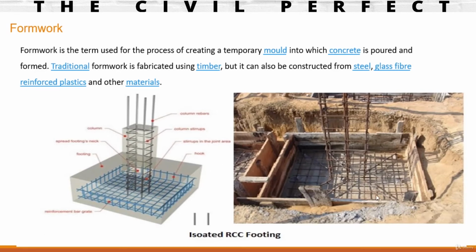Here is the pictorial slide of the formwork. You can see we have an isolated foundation, and this is the formwork for the isolated foundation. Remember that the quantity of the formwork will be in meter square or feet square. If you are finding the quantity in feet, you have to find it in feet square, and in meter the quantity will be in meter square.